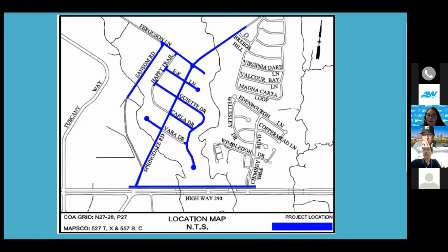With these 2 PRV stations, what it's accomplishing is creating a new pressure zone within our system. Right now, the houses are served by the north pressure zone. The next lowest pressure zone from that is central, which is on the south side of 290. But if they were put onto central, the pressures would be too low. So we're going into basically a middle spot between the 2 pressure zones. We're creating a new pressure zone just for those 2 areas.